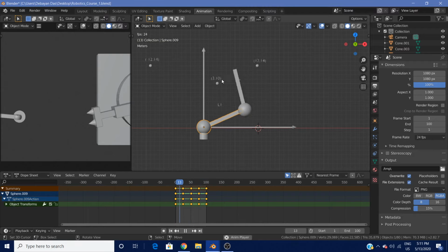So using your Arduino, you would technically do exactly what we did right here. You would find out what the link lengths are, you'd find out what the x and y value is, then you'd find out what the values of theta will be to get to the next point, and you could simply put in those values of theta to the Arduino code, and the servo motors would output exactly that angle. But the actual final motion of the robot would be slightly erratic.